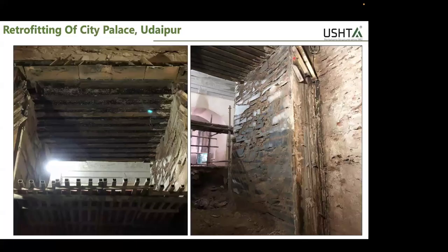And this on the right hand side you see this is the cut portion by wire saw, how smooth it has cut. And this is a 500-year-old structure wall, random rubble masonry in lime mortar, yet you see nothing has come down. And here you see the room which is at higher level, and this is almost 7 feet down.